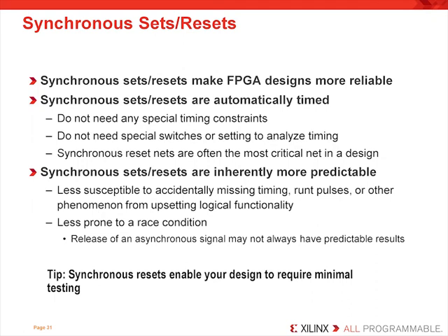Synchronous sets and resets do not need any special timing constraints or timing analyzer settings, unlike asynchronous sets and resets. They also do not require any special switches in the timing analyzer for timing analysis to be complete. Synchronous resets are automatically timed and they are inherently more stable. As you may or may not know, asynchronous resets are ignored by the implementation tools. If you use asynchronous resets in your design, you may not know that they can lead to disastrous functionality.